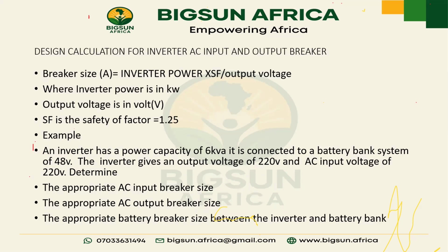I should also mention that when you are going for the next higher one, it should be within range. You don't go where you are supposed to use 120 amps and use 250 amps. The essence of the breaker will be defeated because it's not going to break. You will fry the system before the breaker even notices that the system is being overpowered.